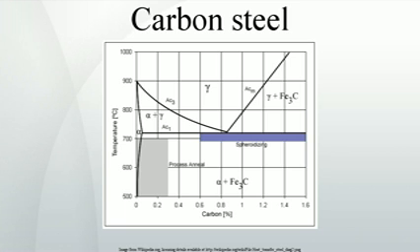Less than 0.3% carbon content, see above. Approximately 0.30 to 0.59% carbon content. Balances ductility and strength and has good wear resistance. Used for large parts, forging and automotive components.